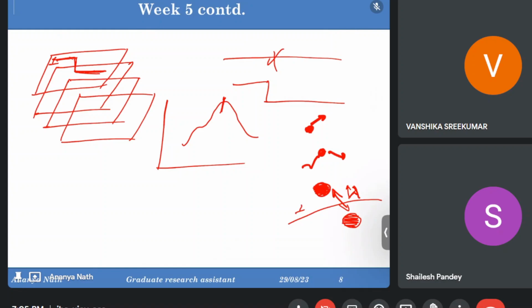Here, the solute atom movement was more important than the dislocation movement, because we were playing with the solute atoms to lock the dislocation. But here, as we are doing cold working, solute atoms are so small that it's one atom. How small it is, it's not even micro, it's a nano scale thing. So we cannot play with the solute atoms in case of cold working, because we are not giving any heat to the solute atoms, and solute atoms are substitutional in case of aluminium.